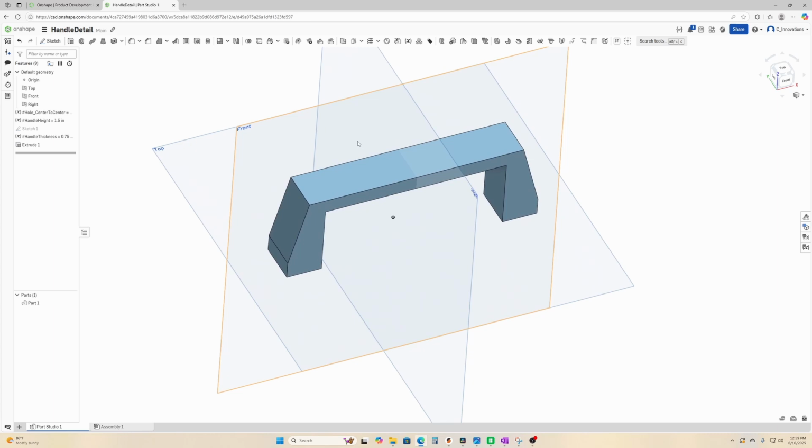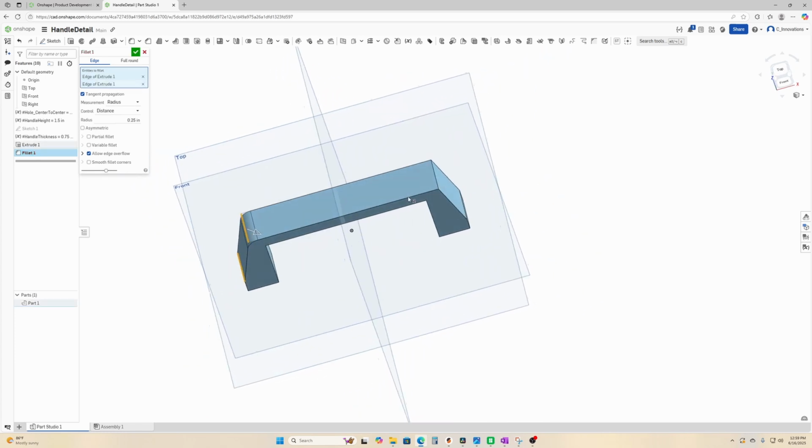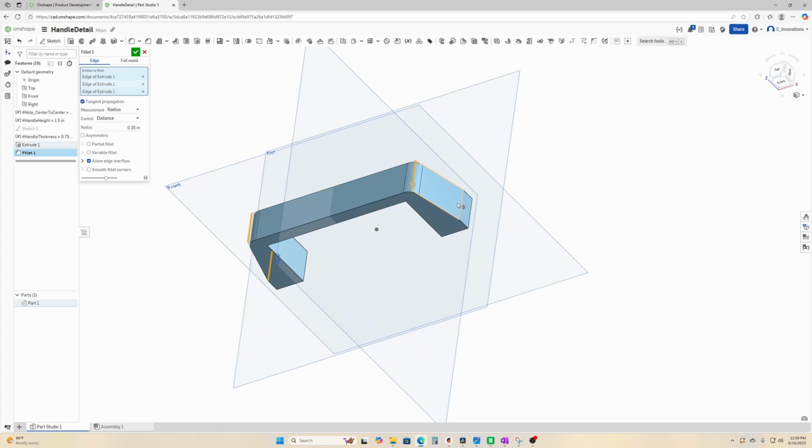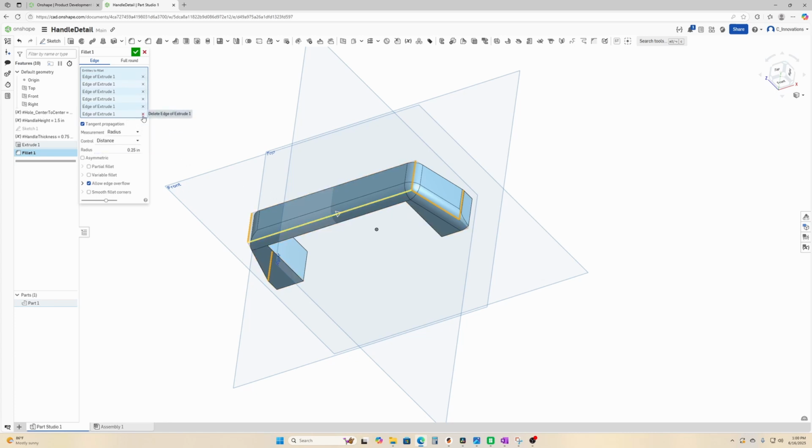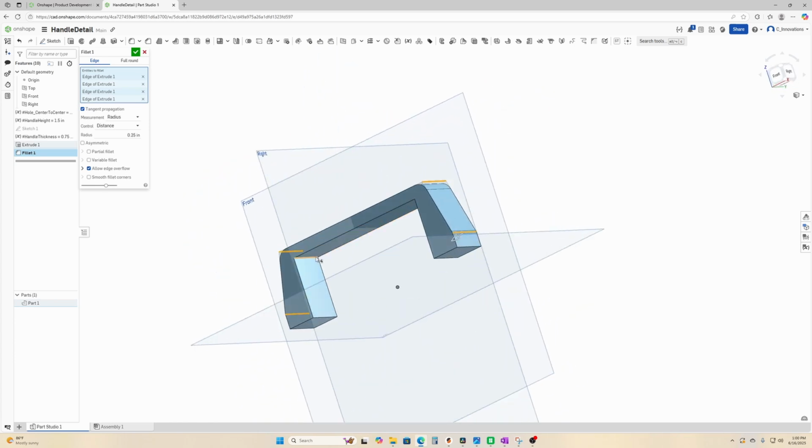Finish that extrude. Now to clean it up like I did the other one, we're just going to add some fillets. Let's go up here to fillet command. Keep it at 1/4 of an inch. Keep it simple for now. We're just going to select those edges. You can do those edges. Let's not do that last one. Let's not do that one for right now. We'll do under here.